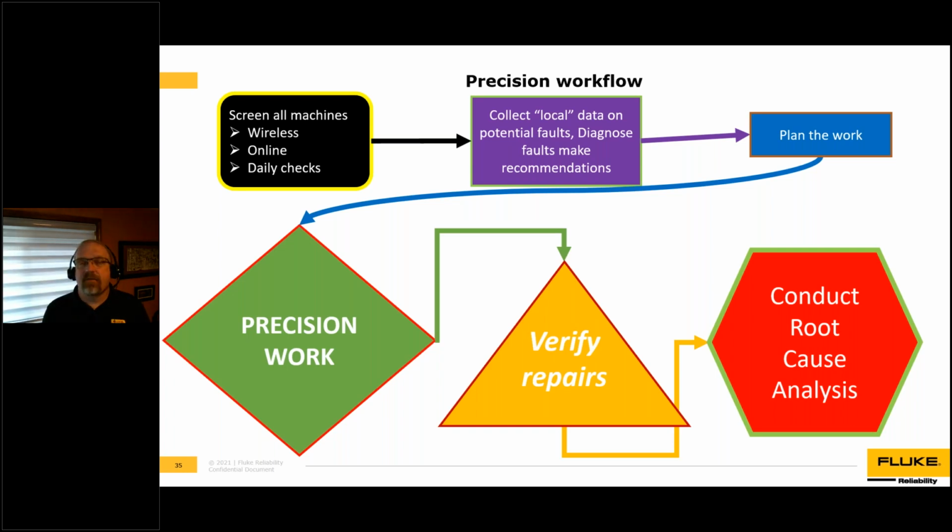And then if you don't maintain your spares and your bearings sit on the shelf for too long, or your motors stay in the warehouse for too long, you may find yourselves with bearing fault conditions developing from conditions like false brinelling.